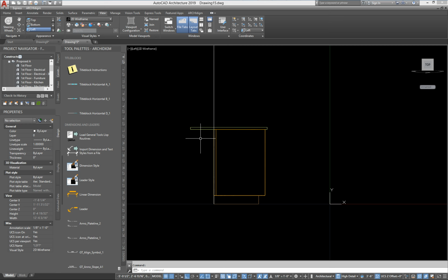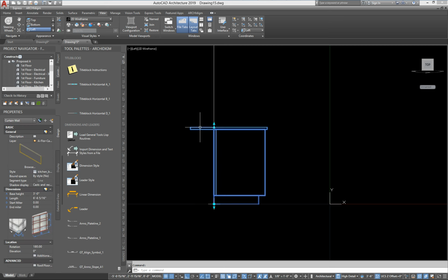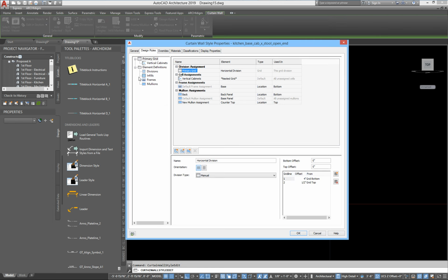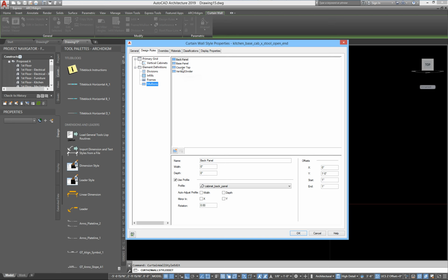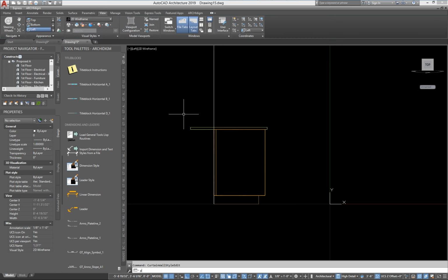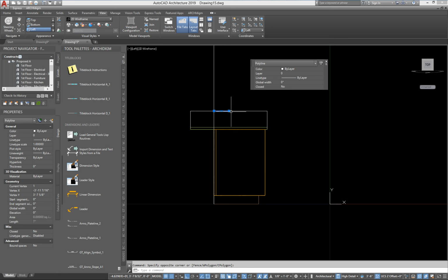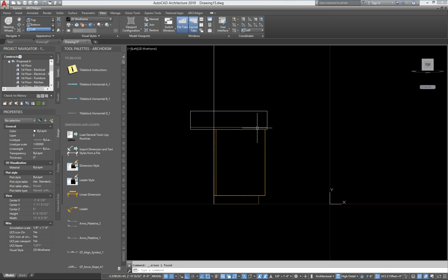So you have to think relative to that. If I go in here, go to the mullion and then the countertop, I have 3 feet with a 7-inch offset. If I draw a line up here like this, 3 feet, and come back down, the 7 inches is going in this direction right there. So it's 7 inches relative to that offset, because I want to push the countertop.